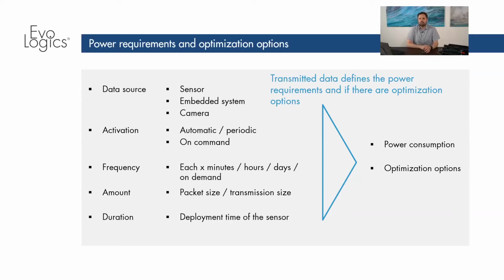Then you need to consider how the system will be activated. In some cases, you have systems that operate only for a few hours to a day or two maximum. In that case, this is not such a consideration. But in some cases, you have systems that need to operate autonomously for 2 or 3 years or even longer. And in that case, it's important to know that the system needs to go to a standby mode, a sleep mode. And then how are we going to get the system to operate? This can be done with either a sensor that activates this device, or we can send acoustic signals.